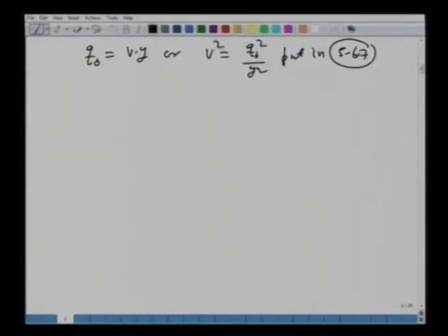So, what we are doing is we are eliminating the velocity v, so that we can get the expression for flow depth, and once we have that we can find out the other one using q is equal to vy. Okay. All right. So, it should be easy to see that your y would be equal to f q0 squared over 8g s naught, this whole raised to the power 1/3.